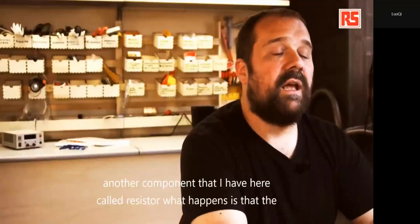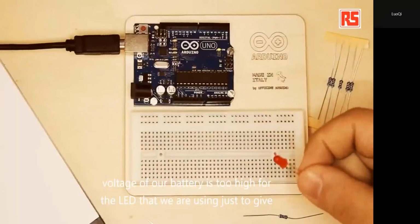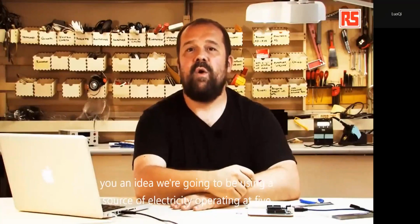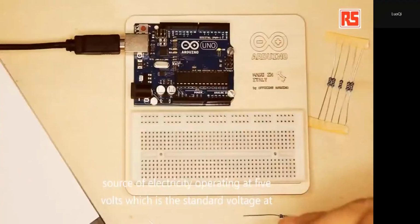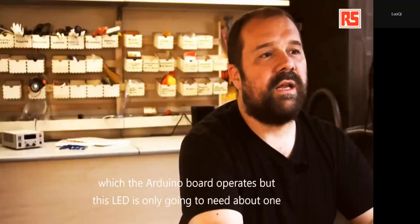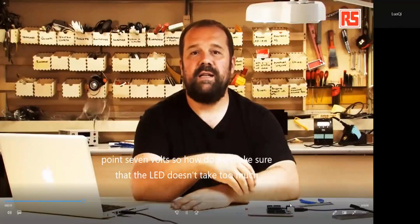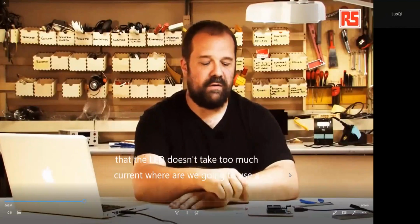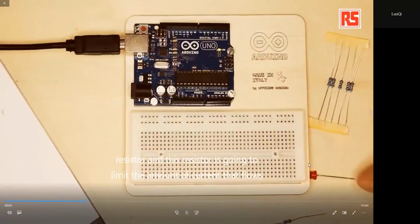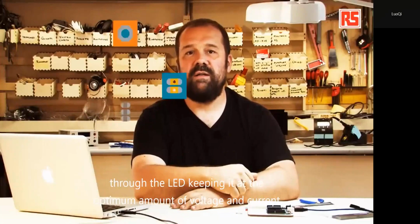What happens is that the voltage of our battery is too high for the LED that we are using. Just to give you an idea, we're going to be using a source of electricity operating at 5 volts, which is the standard voltage at which the Arduino board operates. But this LED is only going to need about 1.7 volts. So how do we make sure that the LED doesn't take too much current? Well, we're going to use a resistor, and this resistor is going to limit the amount of current that flows through the LED, keeping it at the optimum amount of voltage and current.